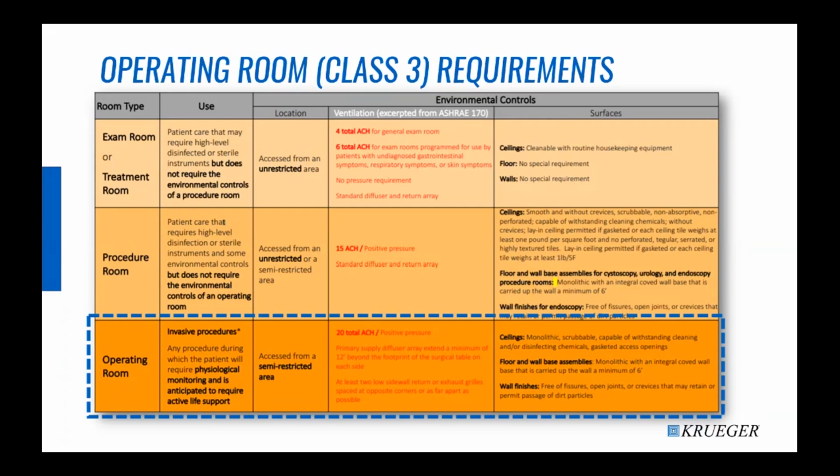The relative humidity for the room should fall between 20% to 60%. You actually don't want your operating space to be too dry, because a dry climate allows particulates to move around the space more easily. Also, the target ambient temperature for the operating room should be between 68 to 75 degrees Fahrenheit, but this can vary based on surgeons' personal preference. Many surgeons prefer ambient room temperature several degrees below the ASHRAE target range.